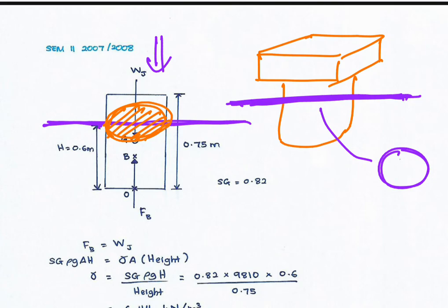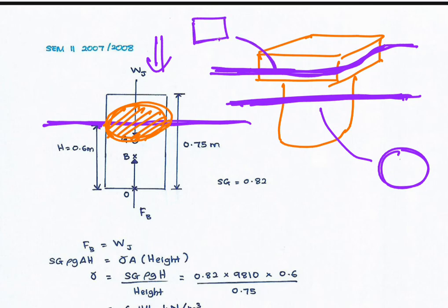If the water rises and it floats until this level, now the shape at the free surface is rectangular, so the I moment should be based on the rectangular area. You need to understand this idea, because you need to determine the equation of the moment of inertia by looking at the area on the free surface of the water.